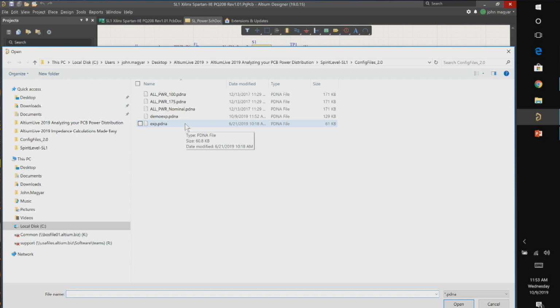situations. Another thing I mentioned is that it's not a typical simulator, where you think you're simulating relative to a time clock. As I said, this is static. So I've seen some pretty creative things where it's a brushless DC motor controller, for example. That's something where one half of the circuit is working for X period of time, and then the other half works for a similar amount of time, but they're never on at the same time. So the scenario you would do is you could make a configuration where one side is activated and then the other, or actually it's three in the case of a motor. There's three phases to that. And you could build up a scenario which measures each one independently. So to get around that absence of time, you can make more configurations to describe a particular condition.